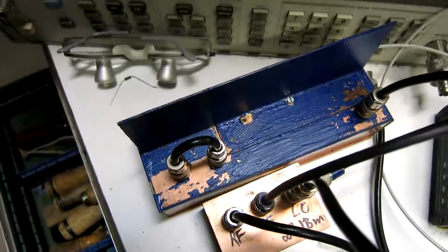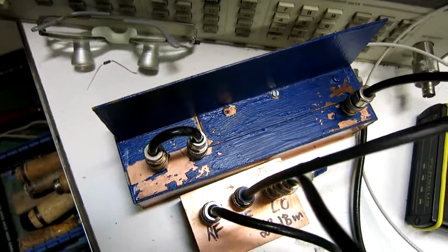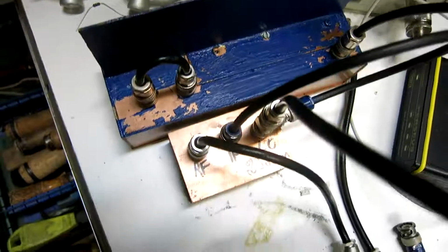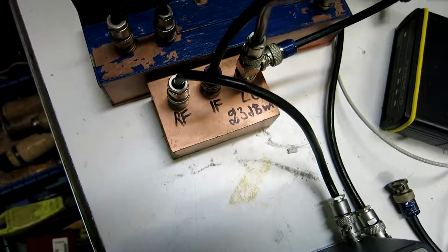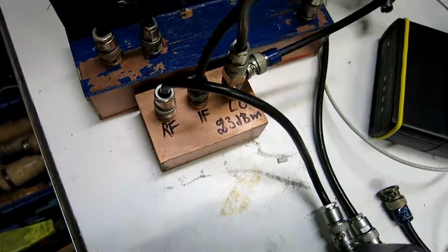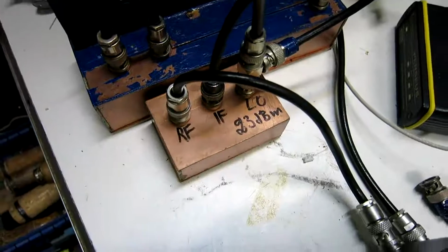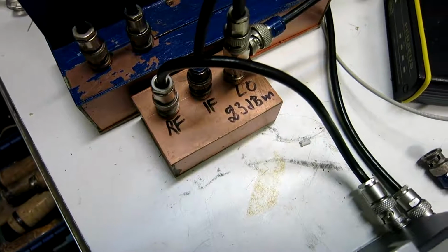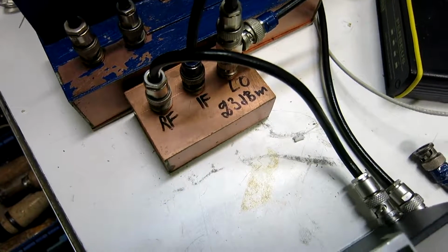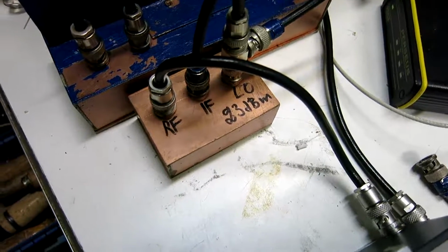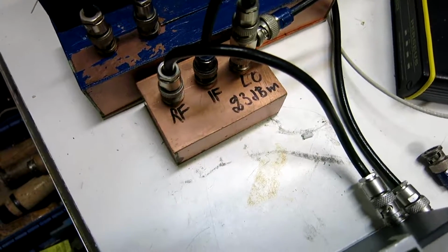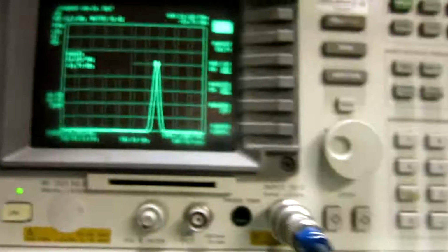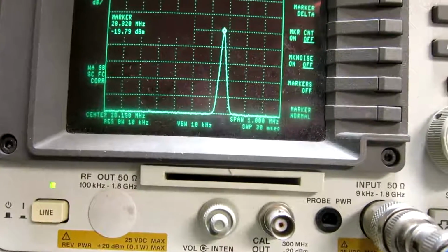I don't have a low noise oscillator for 28 megahertz, but I have one for 14.15, and I have connected it in parallel to two of the inputs of this box here, and inside is a 23 dBm Schottky mixer. The output contains the difference frequency, which is 0, means a DC voltage, and the sum frequency, which means the double, which is 28.3. And then I go through this attenuator again, and up to the spectrum analyzer, and I have set the level to minus 20 dBm.